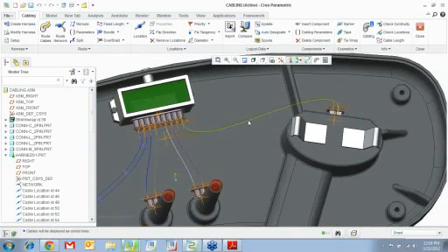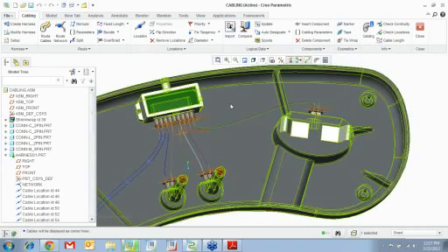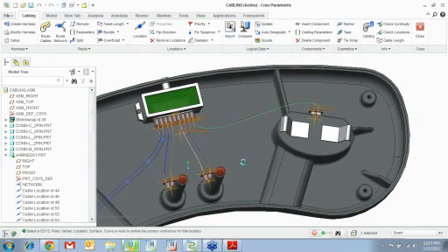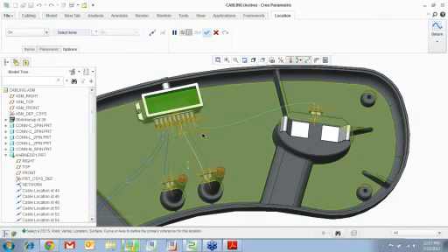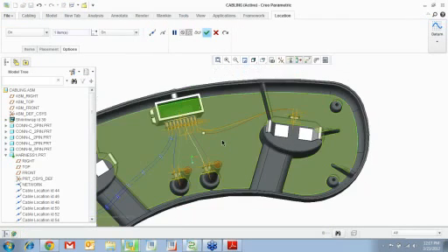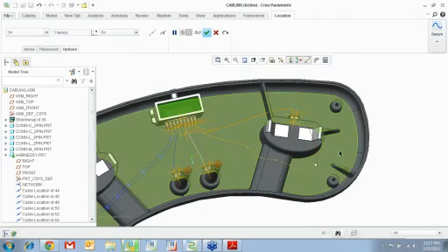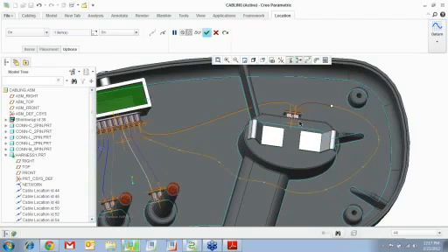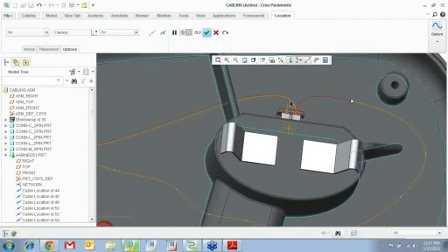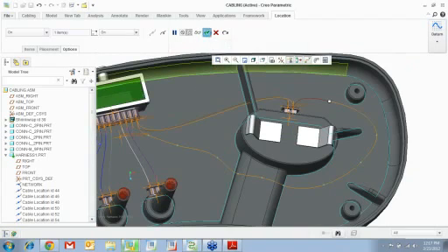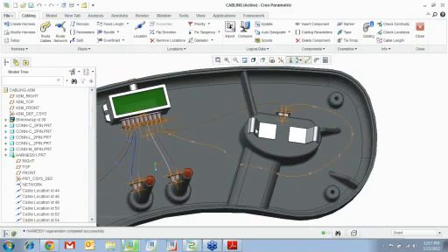So you go select both of them, right click, you just get this. So here you go, insert location, and you want to start off 1, 2, 3, and you can see how your cable kind of follows your location path, right? So there you have your locations, and you can say done. Now we do the same thing for this.